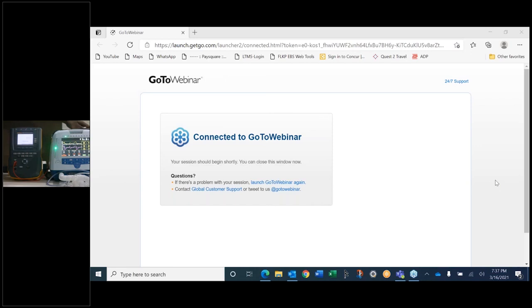So, the touch current. Ravi, that aluminum foil should go on the surface of the medical device that the patient is most likely to touch. Therefore, not on the top typically, but probably on the front face. Okay, can we move it? Can you do that, please? Yeah, we can do it. Yes. We do that one also.